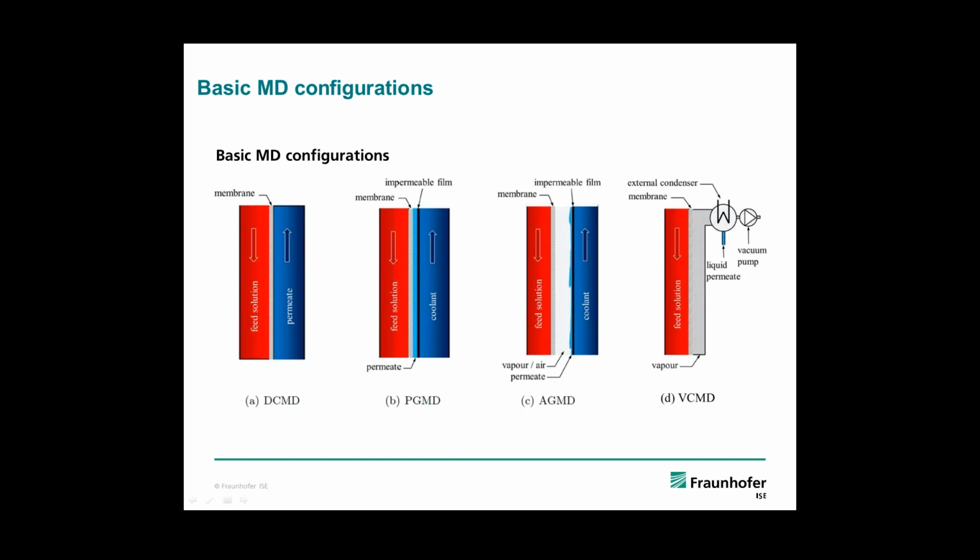And you can see in this graph here how this driving force, respectively the pressure difference, can be calculated from the Clausius-Clapeyron equation. So the blue line, for instance, is the water vapor pressure with respect to temperature. At 100 degrees centigrade, there is the boiling temperature and 1 bar pressure is achieved. So if we assume a temperature difference of 10 Kelvin between the hot feed side, which is probably 90 degrees centigrade, and the cold permeate side, which is probably 80 degrees centigrade, then you see that according to this temperature difference, a water vapor partial pressure difference of about 0.22 bars is established.